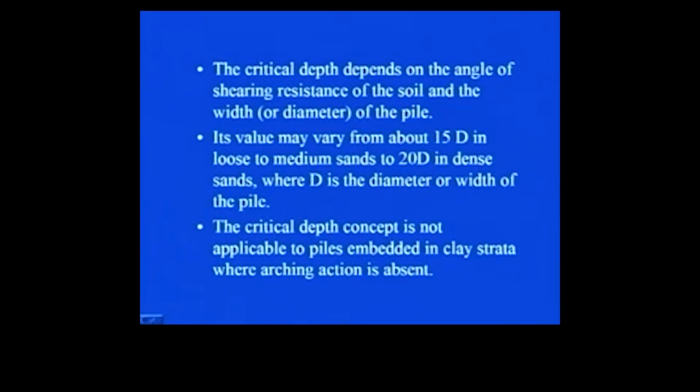This critical depth concept is not applicable to piles embedded in clay strata, where the arching action is absent. So, while you go for soil exploration, you will know what exactly the soil strata below the ground surface is. All these things you do beforehand, before construction of the pile, to get an idea of approximately what the load capacity of the pile under compression can be. So, if the soil strata is granular in nature, you will use this critical depth concept, and if clay is surrounding the pile, then this critical depth concept will not be applicable. In that case, you have to consider the linear variation in which the unit point resistance will be increasing, and take that into account.